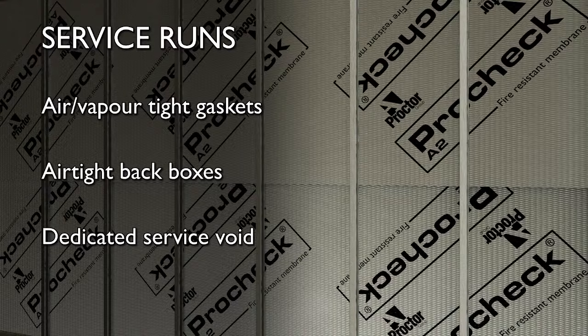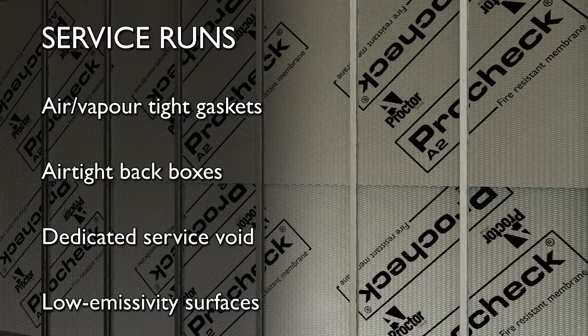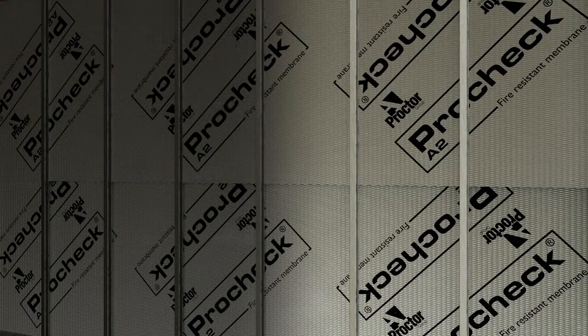If a foil faced membrane is specified, then this service void will also allow the inclusion of the effects of the low emissivity foil surface in thermal calculations, boosting the thermal performance of the element.